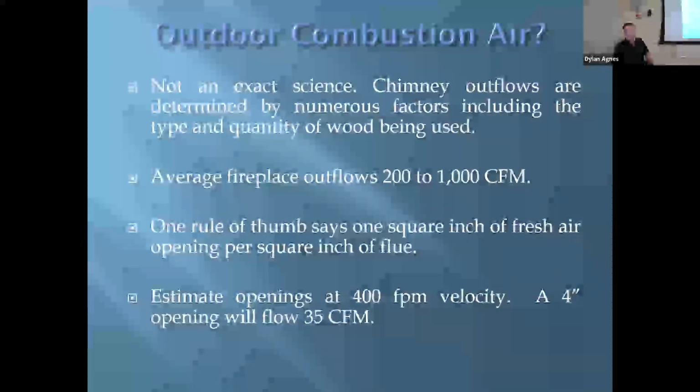So chimney outflows, man, talk about numbers all over the place. I have yet to find an article or a source that gave me numbers that I feel confident using. Trying to measure a chimney outflow is difficult because you can't put a flow hood over it while you're burning a fire.